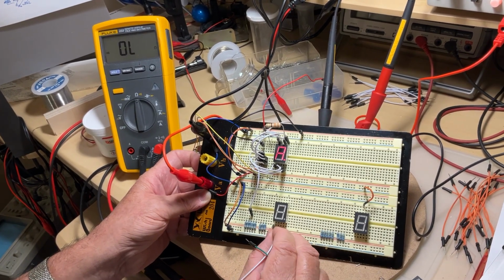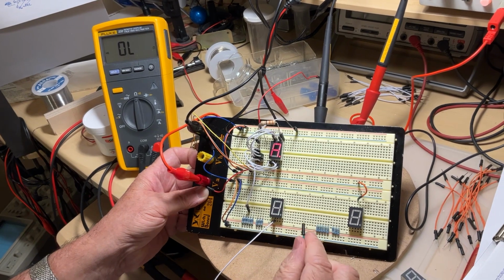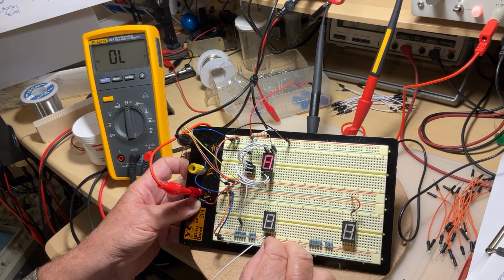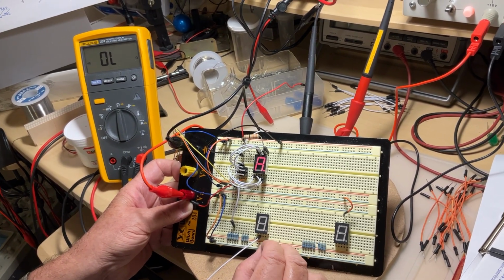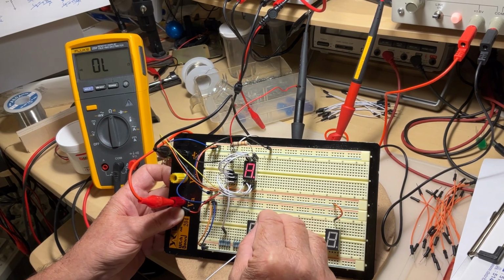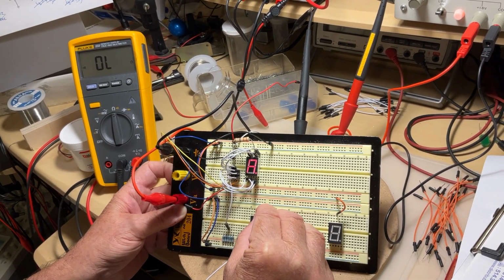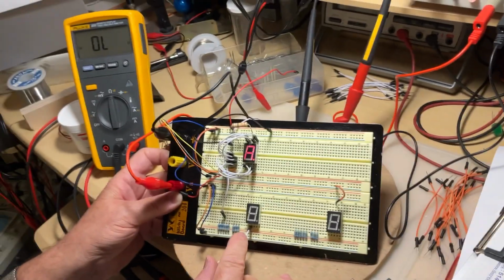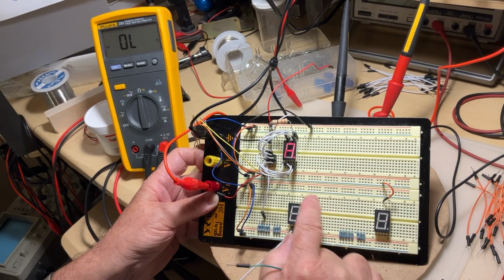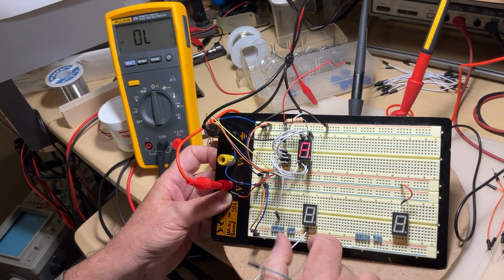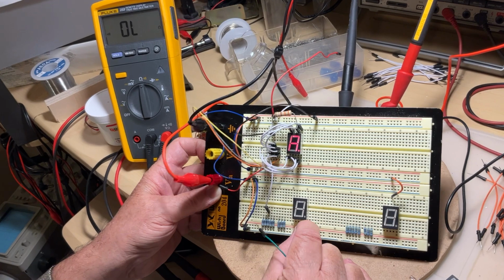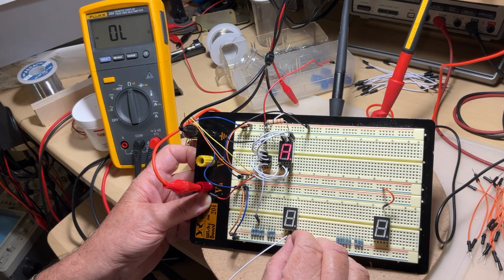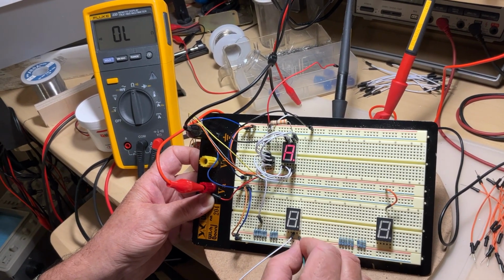In other words, I just found that the pin number 1 surely is not a common. So then I move it on the pin 2 and check again the other pins versus this one: pin number 3, number 4, number 5, 6, 7, 8, 9, and 10. Surely the pin number 2 is not a common because it does not show 0 ohms with respect to any other terminal around the package. Now I move it on the pin 3. You see the pattern here. Now I go pin 4. I don't need to go on the pin 2 because pins 2 and 3 I checked already.